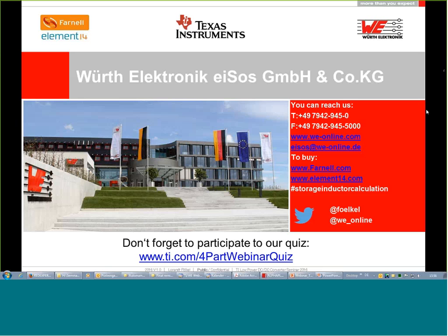In the boost converter, you take the input battery, the source, and you charge the inductance. After you charge the inductance, you put it in series again with the source, the battery, and the inductor current. You put these two, I would say a second battery, the charged inductor, in series, and then you put that to the output. Automatically on the output you may have a higher ripple than on the input, because the input is always flowing. You put additional current to the output, so the current flow is much smoother, and you don't have this reflection.